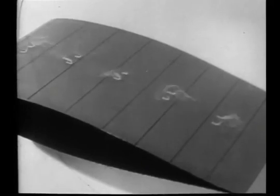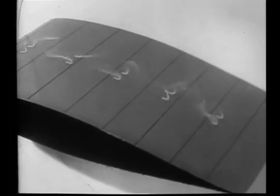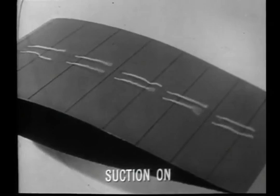The extension of attached flow can readily be achieved if sufficient suction can be applied upstream of the separation point. But if suction takes place entirely within the separated area, the suction quantity required for reattachment may be excessive. The flow over this profile is completely separated, as shown by the violent action and upstream direction of the tufts. Suction reattaches the flow.